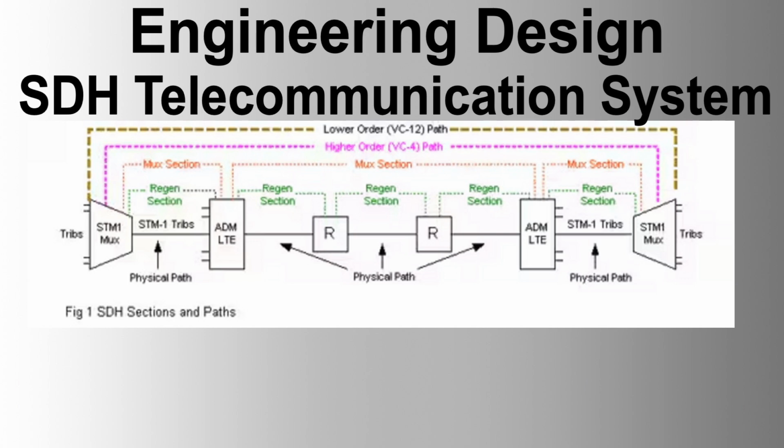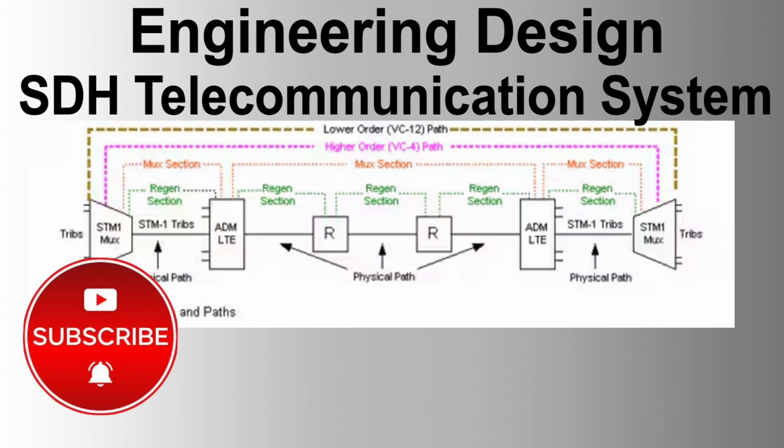Cross-connection capability. Cross-connect capabilities. The STM16 multiplexer shall be able to cross-connect various data streams, including VC4, VC3, VC12, Gigabit Ethernet, and 10/100 Mbps Ethernet in multiple configurations. Technologies utilized. The cross-connect capability shall utilize GFP, VCAT, and LCAS technologies to maximize bandwidth usage and ensure undisrupted traffic.